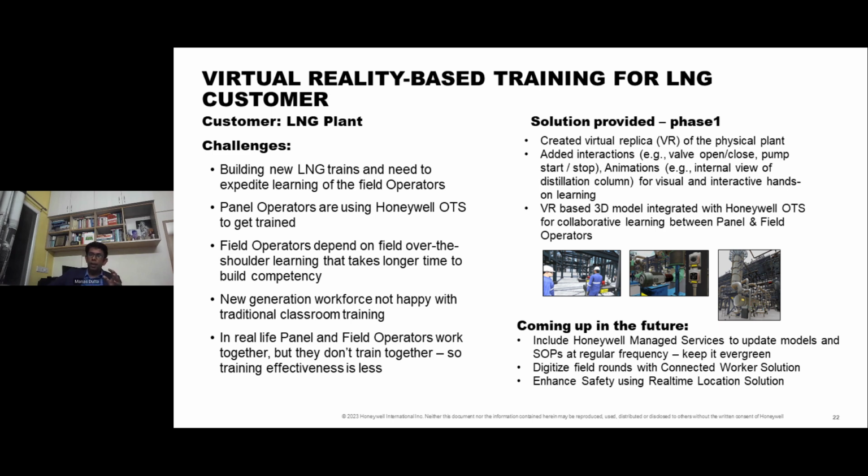So that was the starting problem, and then also bringing the learning of the panel operator and field operator together. So we started with giving them virtual reality as the starting point: let's create the virtual replica of your physical plant and integrate it with the OTS, so that if a panel operator does something in the OTS, operator training simulator, we see how it impacts the field, and vice versa. If a field operator makes any mistake in the field, how it can impact the process. So that was the first phase, which was delivered.